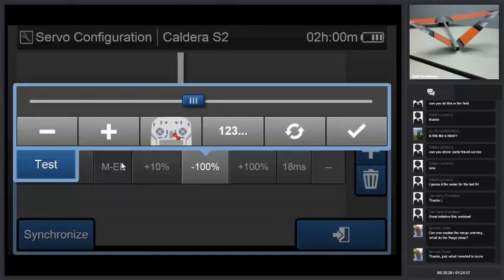And now we go ahead with the limits. So we go here for the servo limit, press the test button and see how the flap is moving. And you can put the value according to your mechanical requirements or mechanical limits. And also you should put the value according to the aerodynamical requirements. So usually the producers of the models give certain values, like you need 5 millimeters for elevator and 7 millimeters for rudder, and you add them and then you just set the value according to what is necessary.